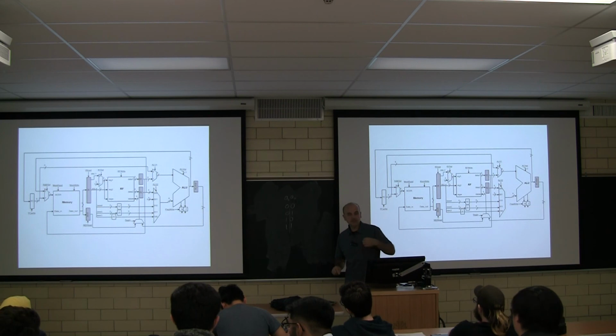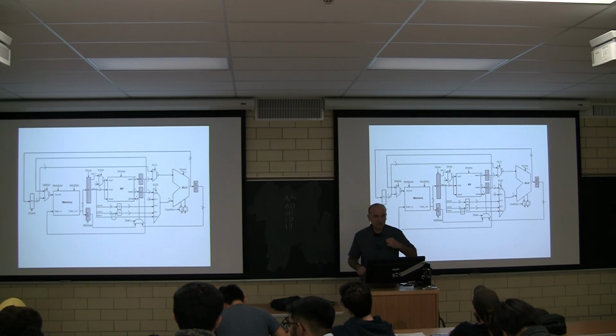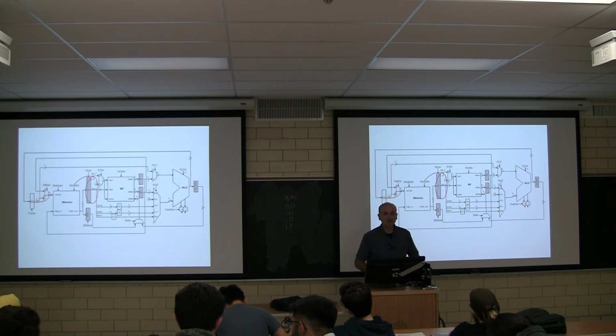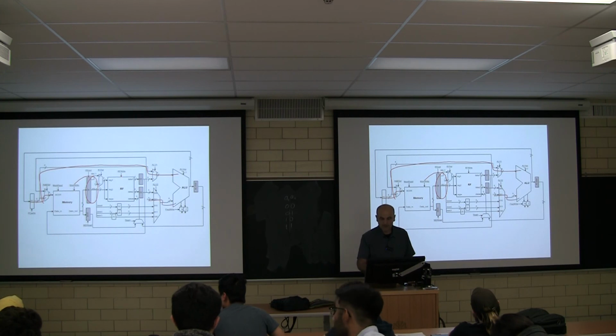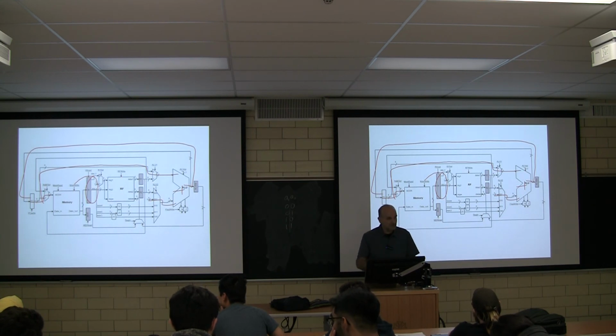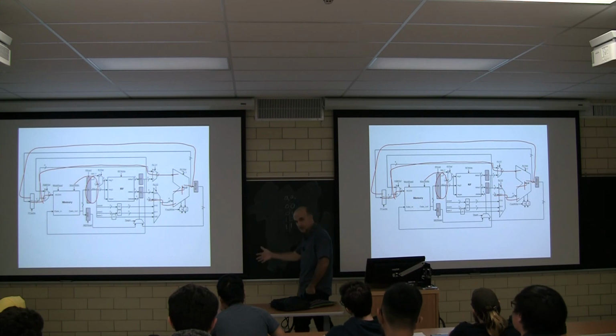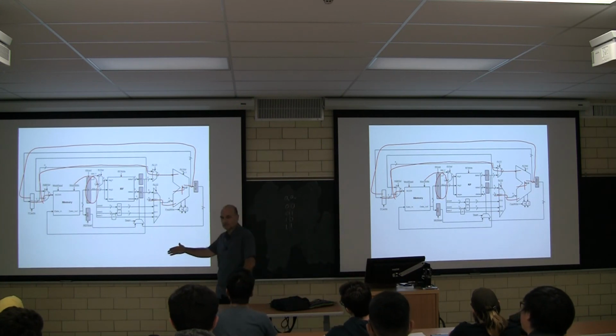The difference here is the following. In the first clock cycle before, we're just taking this value here and reading the IR. Instead, as I showed you in the first table, what we could do in parallel, we can also do this. We can send it to the ALU because the ALU is still there. We can pass 1 over here and do plus 1 and send the result back. So now we're doing both fetch the instruction and PC plus 1, which fits the table I showed you before. So this is an optimization, and I should have described it like that.